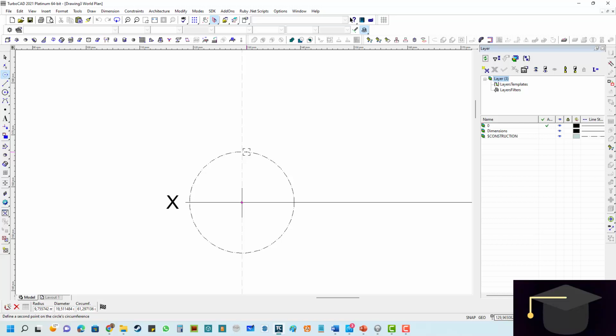And I want it to also be 10 millimeters in front of the XY, or in front of the vertical plane. So I'm going to press tab so that I can give a value to this measurement, and I'm going to say 10 millimeters and enter. Now I can go to this button on the left-hand side, which is for placing a reference point.